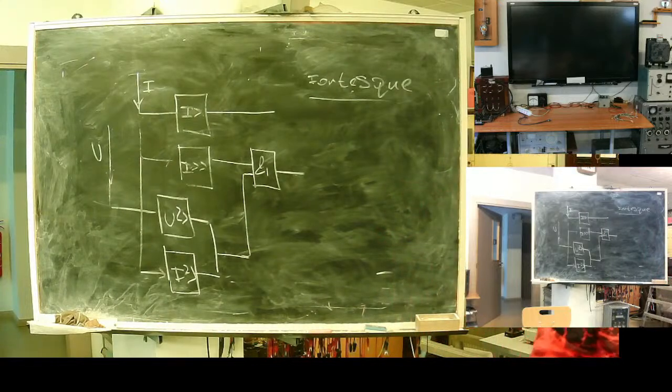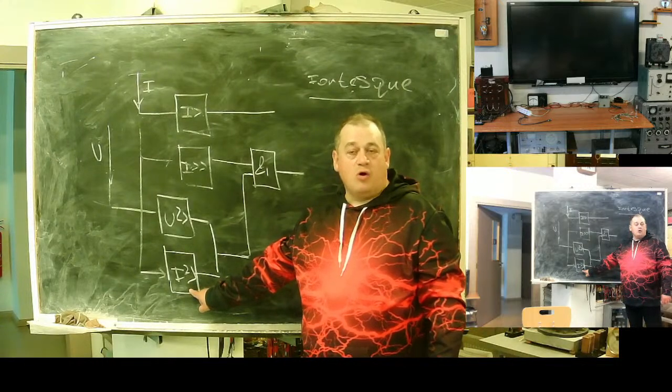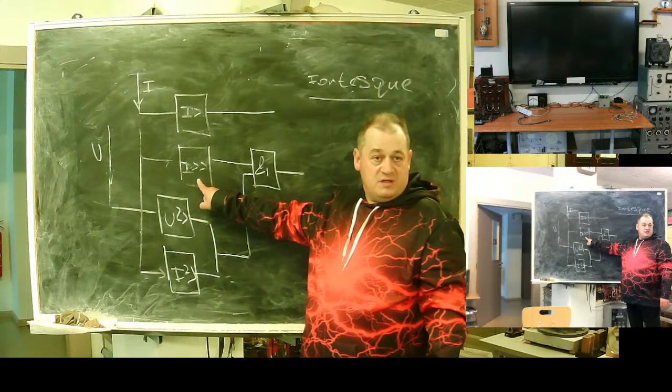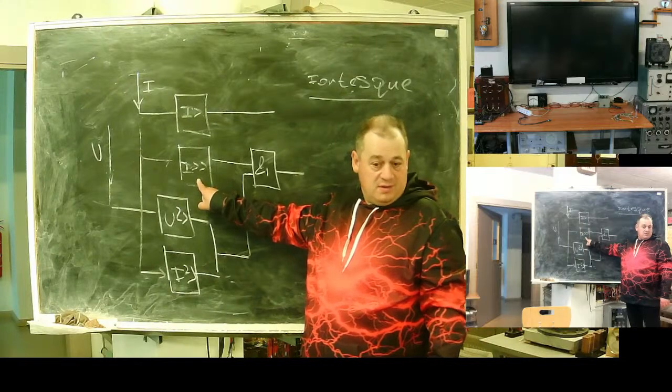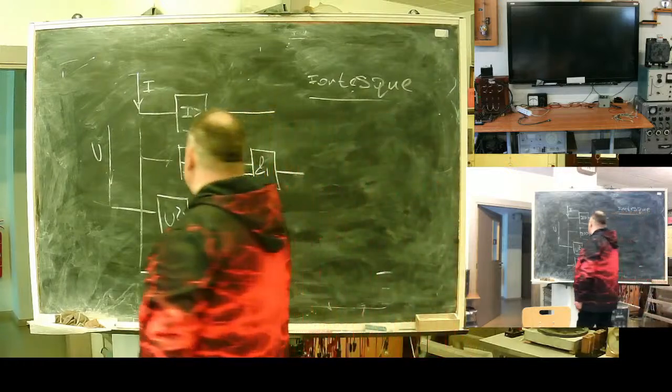While load current and startup current of the asynchronous motor is symmetric, it will not contain negative sequence. Fault current is not symmetric. You have a line-to-line fault. So in case of fault, this relay will trip and will allow you to operate this thing like there is no load current, calculated purely on fault regimes.